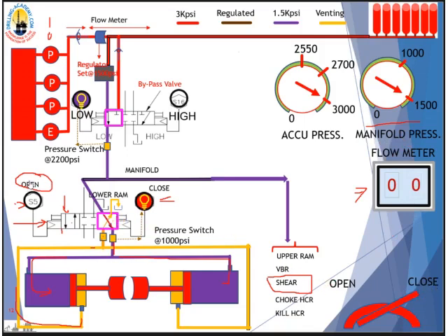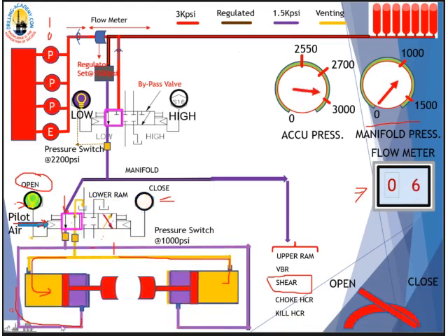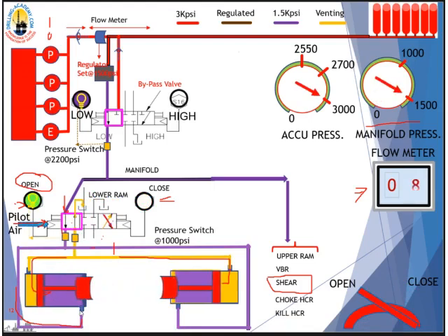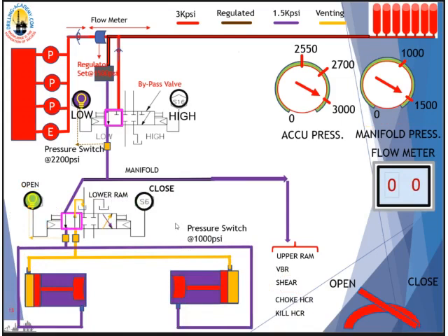Now let's take a look when we press open. And now let's see the magic happen, right? All right, see the line is changing state from vent to pressurized and from pressurized to vent. And the light bulb is lit up here. See, that just happened in a snapshot, right? And now what happens if we close the ram BOP? All right, at the moment the ram BOP is in the open position. We release a button, the valve stays at the last position where it was before.